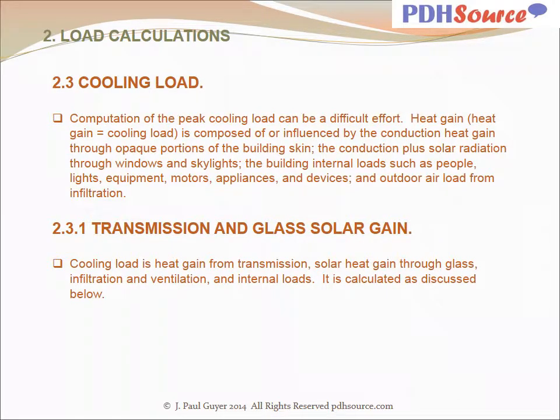Now, with cooling load, the computation of the peak cooling load is a bit different. And this is calculated, of course, during the cooling season, which is the summer. The considerations in calculating the cooling load first are the transmission and glass solar gain.